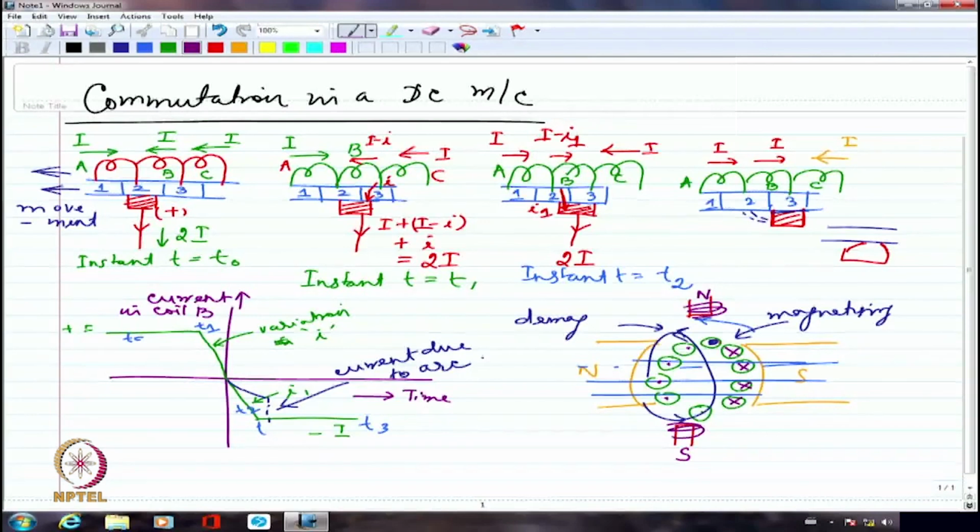Now what you are trying to do is to nullify the effect of the armature reaction flux, which is in the interpolar region alone. We already talked about compensating windings, which will be put on the pole shoes. The compensating windings are meant for nullifying the cross magnetization. The interpoles are meant for nullifying the demagnetization and magnetization effect of armature reaction, right?